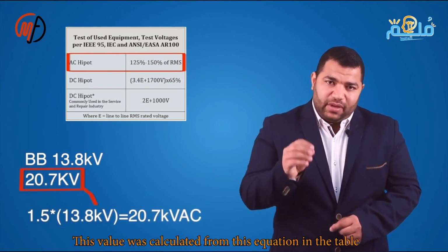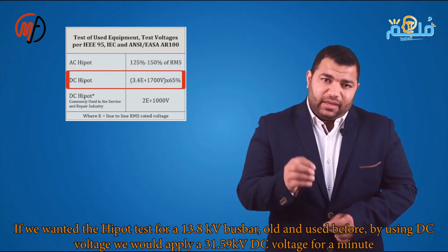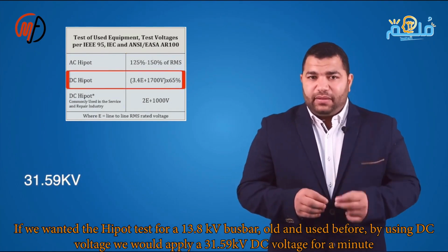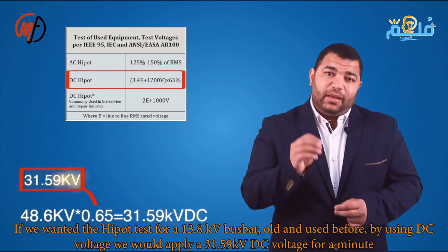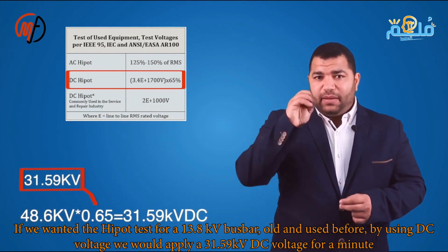It is 1.5 times 13.8 kV. However, if we want to apply a DC voltage, we apply a voltage of 31.59 kV. According to the equation, the applied voltage in the case of used equipment is equal to 65% of the applied voltage in the case of unused equipment.